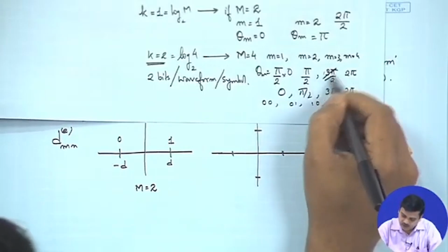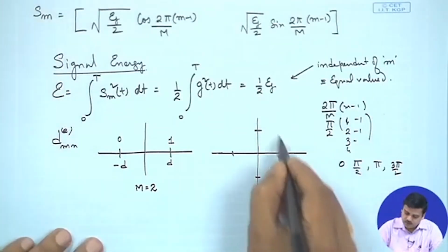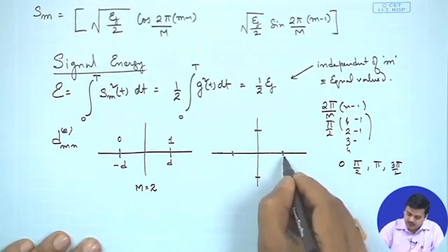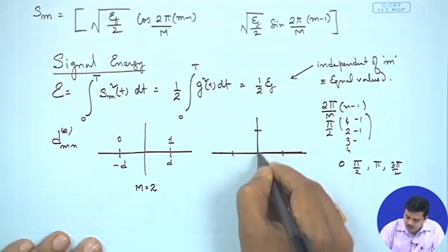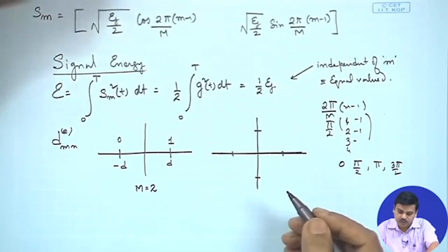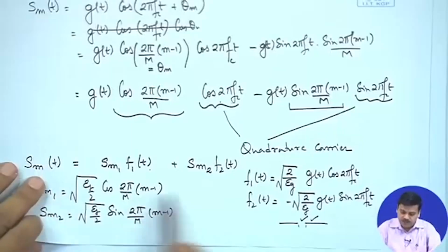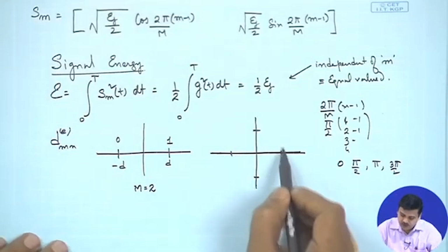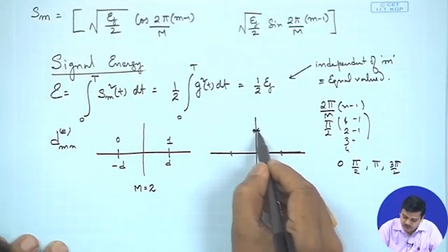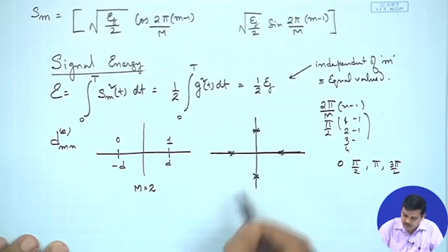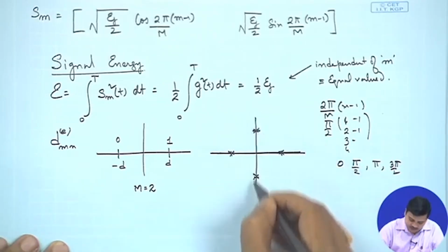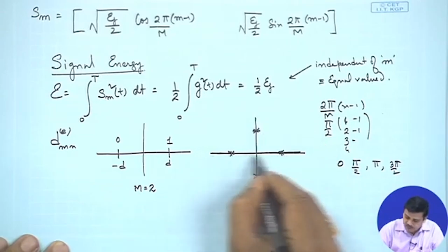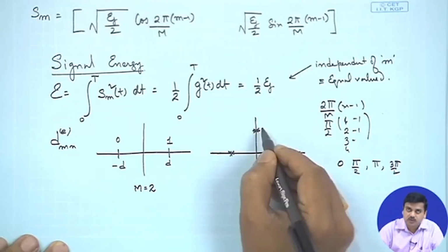So, there is a small change over here. These are the angles that you would get, and now you note that it is no longer a one dimension signal, and that is also clear from the expression that we have over here. From the signal space it is also clear, because you are going around in 2 pi, you are selecting these angles. You could also say that if this is my I axis, this is my q axis, then I have two options in the I axis, I have two options in the q axis.